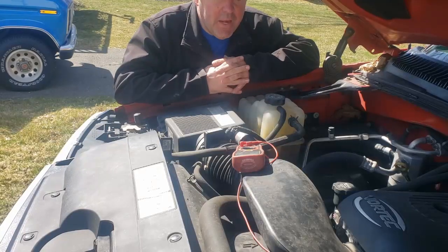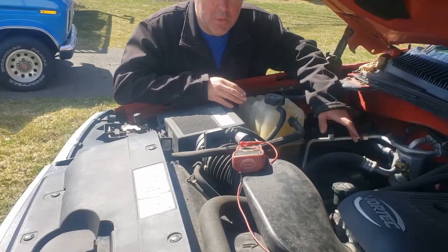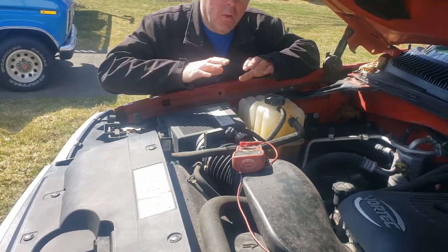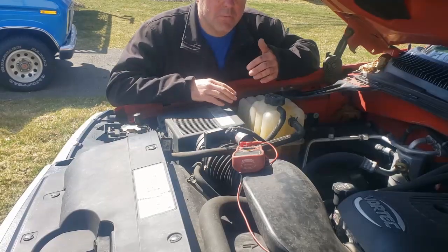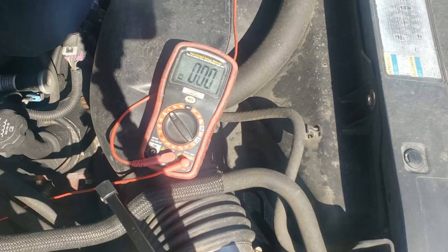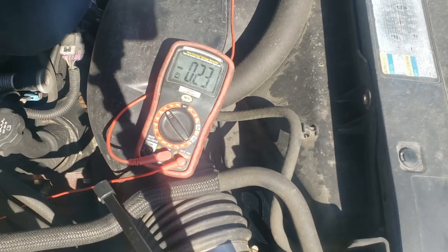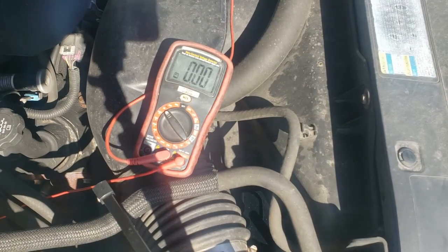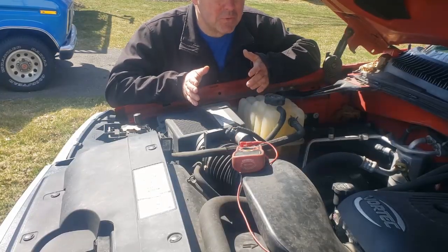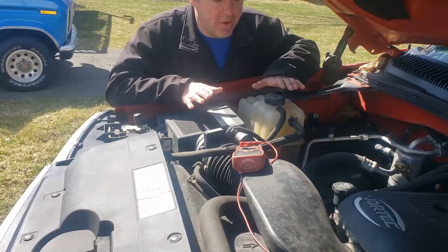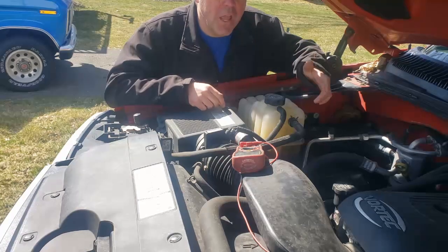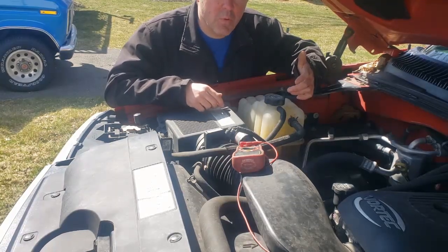Currently I have my meter connected, one end to the battery cable on my starter motor, and the other end to the positive side of my battery. When I'm cranking my engine, remember, I'm looking for the lowest amount of voltage drop possible. During that crank, notice we saw approximately 0.2 volts, about 200 millivolts of voltage drop. Very, very minimal. That tells me that my connection between my battery and the positive side of my starter motor is very good, and everything is functioning as it's supposed to be, which is what we want to see in this case.